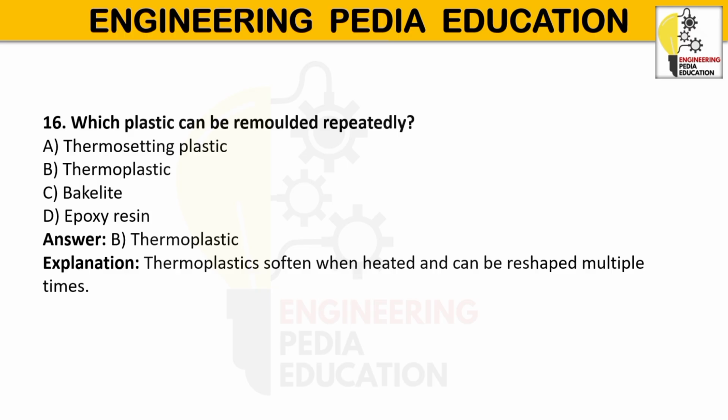Thermoplastics are manufactured from polymer resins and can be molded into different shapes using processes such as injection molding and extrusion. They are lightweight, resistant to moisture and many chemicals, and have good electrical insulating properties. Some examples of thermoplastics are PVC, PE, PP (polypropylene), acrylic, and nylon.